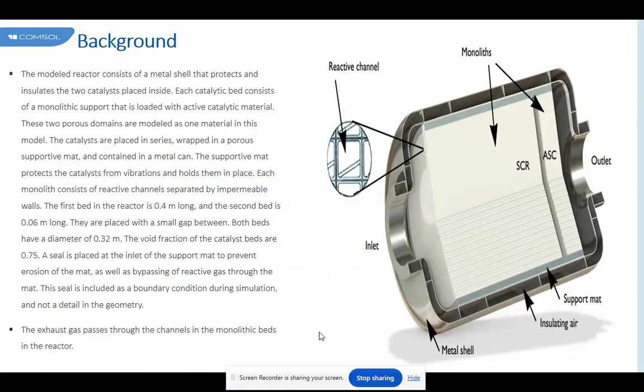On the other hand, for cases B and D, where the core and ring had different cell densities, the fluid distribution was largely affected by the combination of the cell densities. The role of the diffuser is to spread the plume more uniformly across the face of the monolith. However, usually the majority of the fluid remains concentrated in the central section. Therefore, one might expect that, regardless of the cell densities used, the bulk of the fluid would pass through the central zone. However, we observe a different behavior.